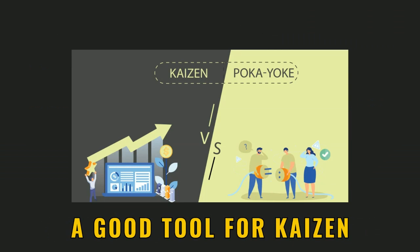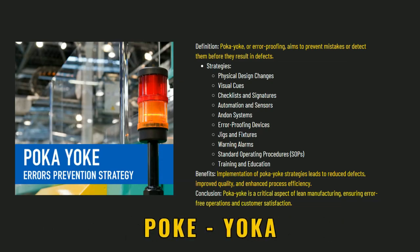Now, a good tool for Kaizen is something called Poka-yoke, however you want to classify it. It basically means mistake proofing, and it's an error prevention strategy. Poka-yoke, or an error proofing method, aims to prevent mistakes before they result in a defect. Some strategies would be physical design changes, visual cues, and checklists and signatures for approval before going to the next step.